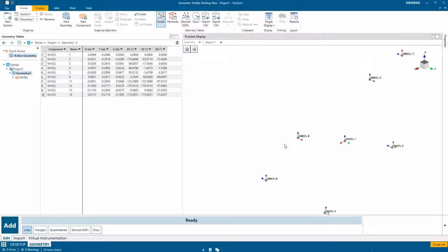And so my displacement shapes, my ODS shapes or my mode shapes will all be the correct phase because I'm graphically aligning those transducers as opposed to just saying, oh, just put them on, and the person mounting the accelerometer decides, well, it's easier if I have the cable coming out this side.